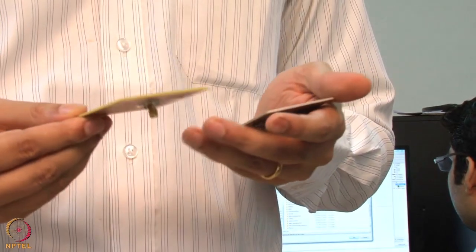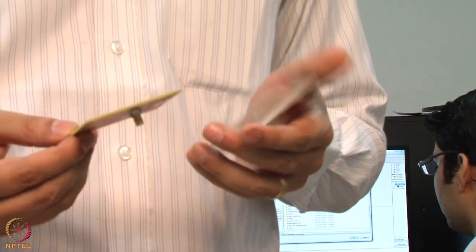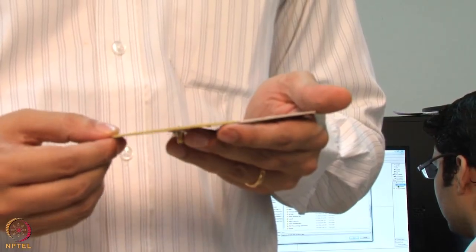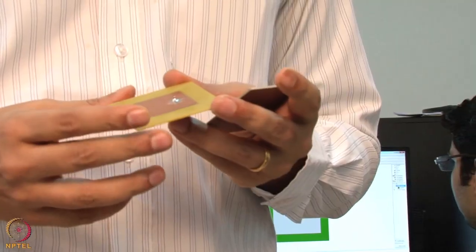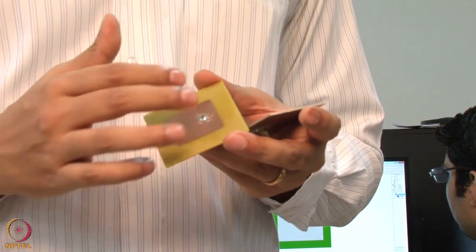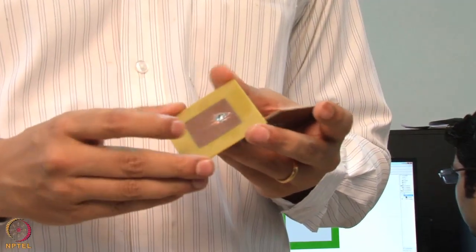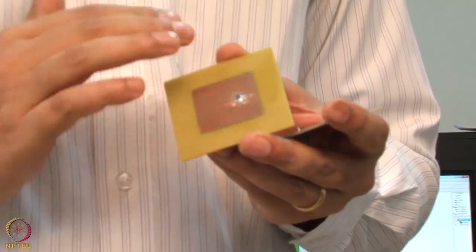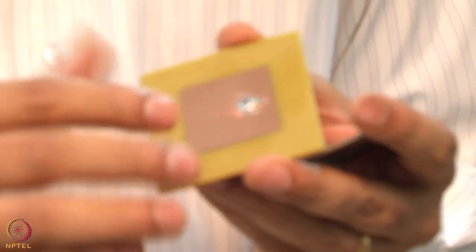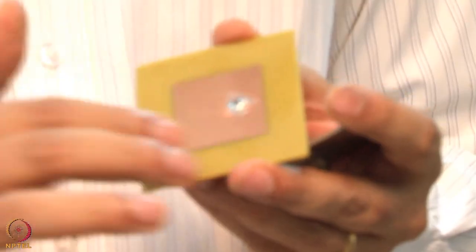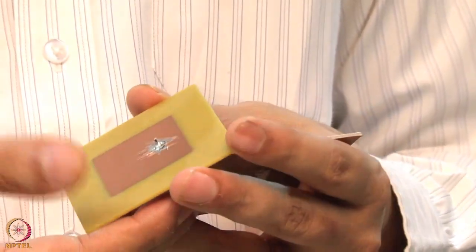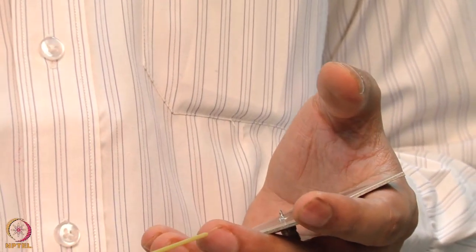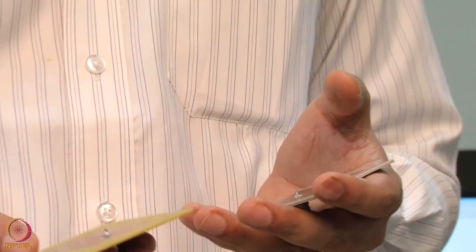We are going to simulate this kind of antenna using the method of moments. The reason we are going for the method of moments is that the phenomena we are interested in for this kind of model are surface phenomena. So we are not going to discretize the volume, we are only going to focus on the surface aspect. That way we can get the best result in terms of accuracy and computational time.